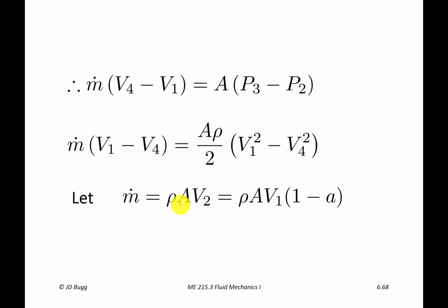So that's the mass flow rate evaluated right immediately in front of the rotor plane. Well, this V2 we can write in terms of our axial induction factor as V1 times (1 minus a). So we want to get this axial induction factor into this equation because it's a very important parameter, as we'll see, governing the performance of this thing.